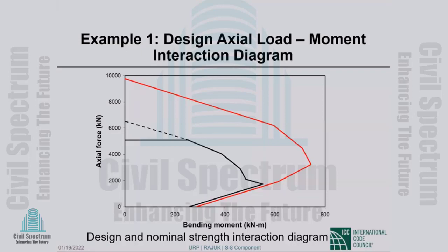And the best way to relieve congestion in the joint is deeper beams. Most architects will not quarrel with that, so there are ways of reducing congestion in the joint, and that's what you should be looking for. What I'm trying to say is the problem should be solved at the design office, not at the job site. By the time you are at the job site, it is too late.